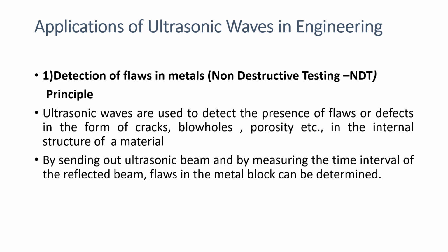It is non-destructive testing. Without destroying the test piece, this detection of flaws in metals is possible. Ultrasonic waves are used to detect presence of flaws or defects in the form of cracks, blowholes, porosity, etc. in the internal structure of a material.